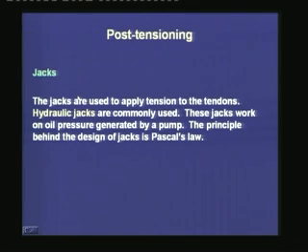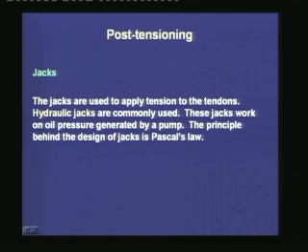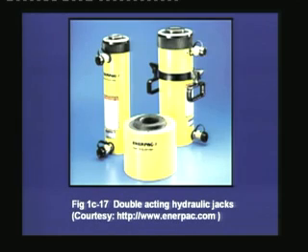Now during the tensioning operation, the jack is the most important equipment that we need. As I said, there can be several types of devices for applying the prestressing force. The most common is the hydraulic jacks, which work on the principle of oil pressure. The design of these hydraulic jacks is based on Pascal's law. This photograph shows some double acting jacks.